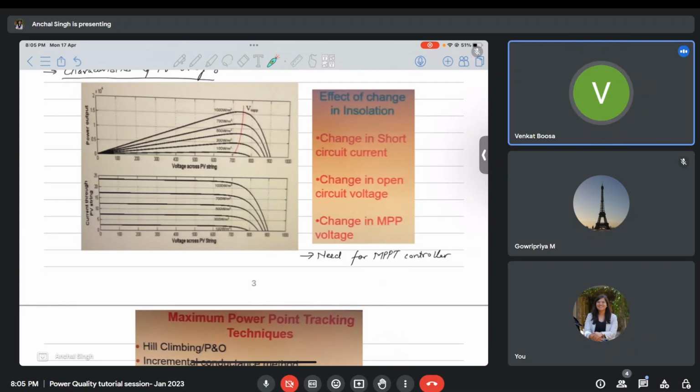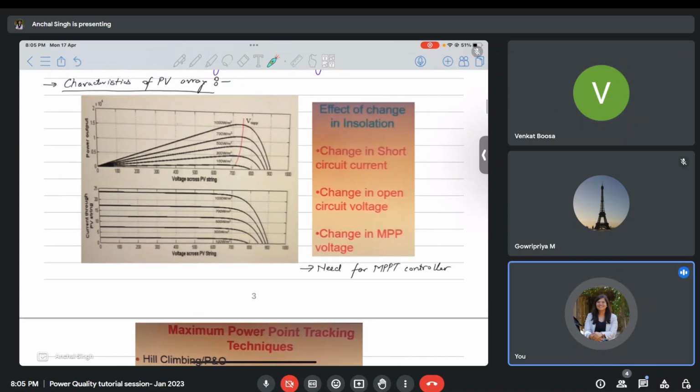What is the maximum power point tracking, madam? That only, na sir. I just explained, right? This is the power versus voltage curve. This is for a particular amount of light that is falling on my solar panel. This is the peak power point, right? In this curve, this is the peak most power that I can get.